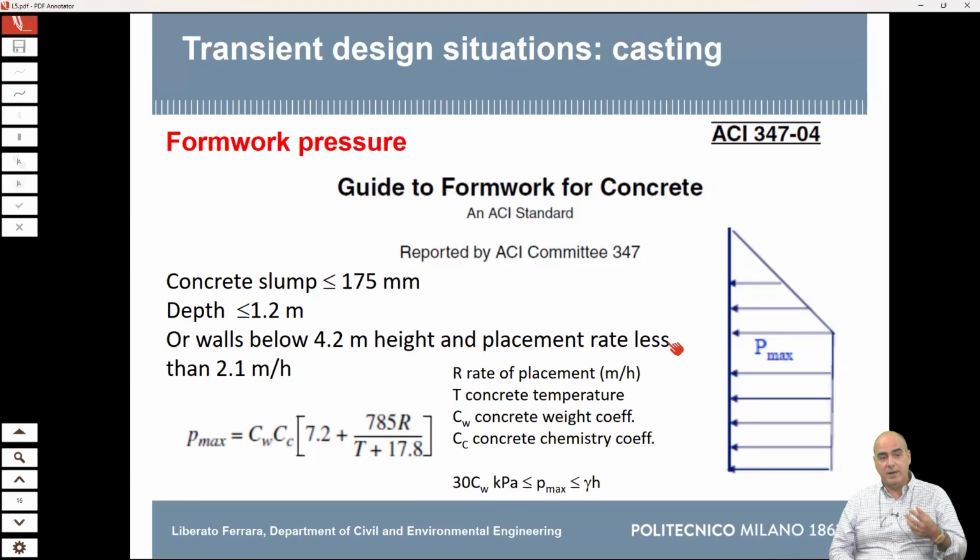But concrete is a granular material whose characteristics evolve over time. So it is considered that as long as you cast and rise up with your volume, the bottom part stays undisturbed. And when concrete stays undisturbed, and you don't disturb it more, it starts setting. And this reduces the pressure because a network forms and it does not behave anymore as a fluid.